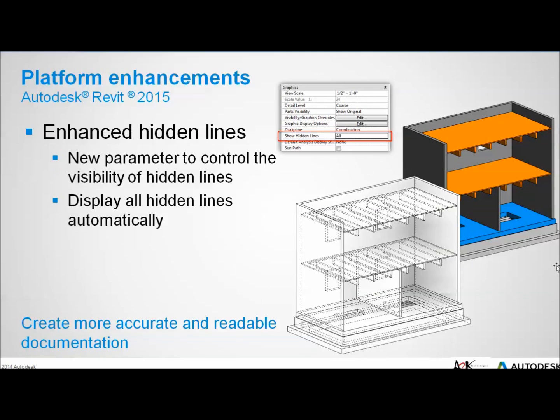Also available now are the hidden lines. These now allow greater flexibility to actually see a lot of the hidden work between 3D views, and also can be used for structural steel elements. Once you look at these, you'll probably find these very useful, as mentioned, especially when it comes to steelwork.